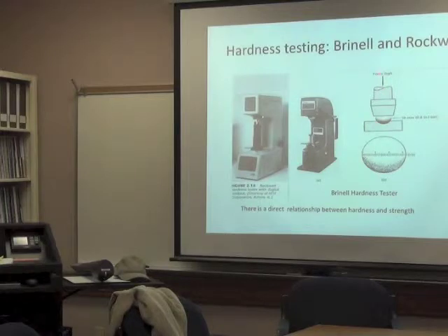Then they apply a force from the top, and of course you make an indentation in the material. You can use a little eyeglass with a vernier scale on that, and you can measure the diameter of that indentation.